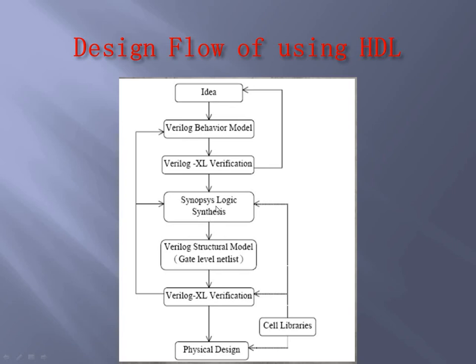Synopsys is the tool which is used for the logic synthesis. What is synthesis again? Converting your program into a netlist. And you are again verifying the structure here, because when it gives you a list of components, it is nothing but the group of components connected together to make up your circuit. So we call it the structural model, and then you verify it.